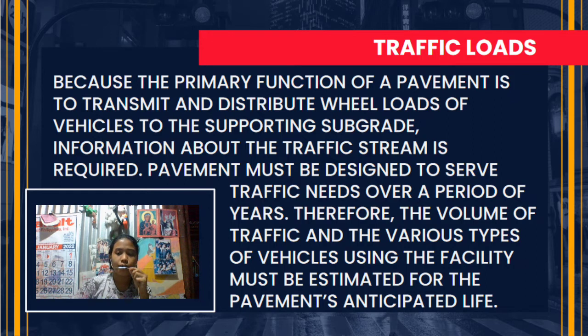So, traffic loads. One of the primary functions of a pavement is load distribution. Therefore, in order to adequately design a pavement, representative loading characteristics must be presumed about the expected traffic it will encounter. Loads, the vehicle forces exerted on the pavement, like trucks, heavy machinery, airplanes, can be characterized by the following parameters. First is individual tire loads, axle and tire configurations, typical axle load limits, repetition of axle loads, traffic distribution by direction and lane, and traffic projection: current volume and growth rate.